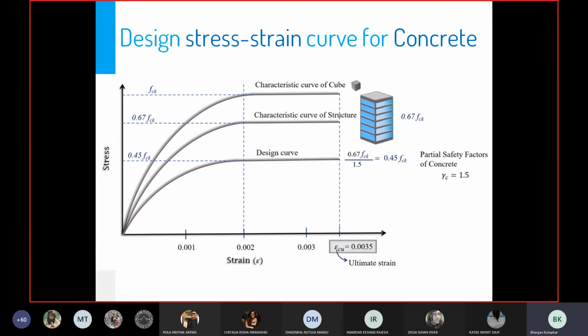It is simply based on hand calculations, and in general the understanding of the contractor with his experience. So if I say, okay, use M25, the contractor might have used M20 before. He'll just say, yes, put a little more cement. That is what happens in the majority of buildings. Again, there's a lot of variability. So who is going to account for all this? That's the partial safety factor.